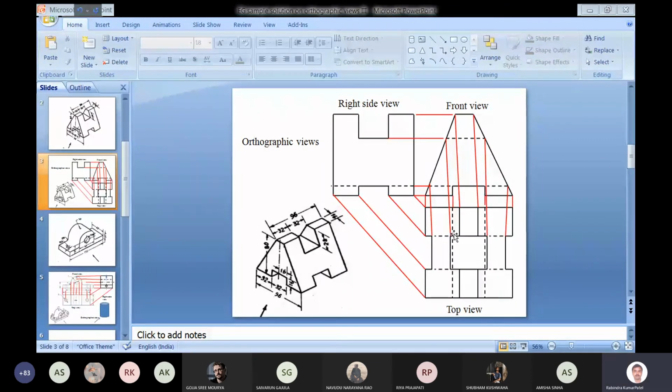Although the dashed line may continue into the hidden portion, here we will not continue it, to show the differentiation from where the continuous line is starting. If we show the dash here, it may seem that the continuous line goes up to this place, which would be a reading mistake.